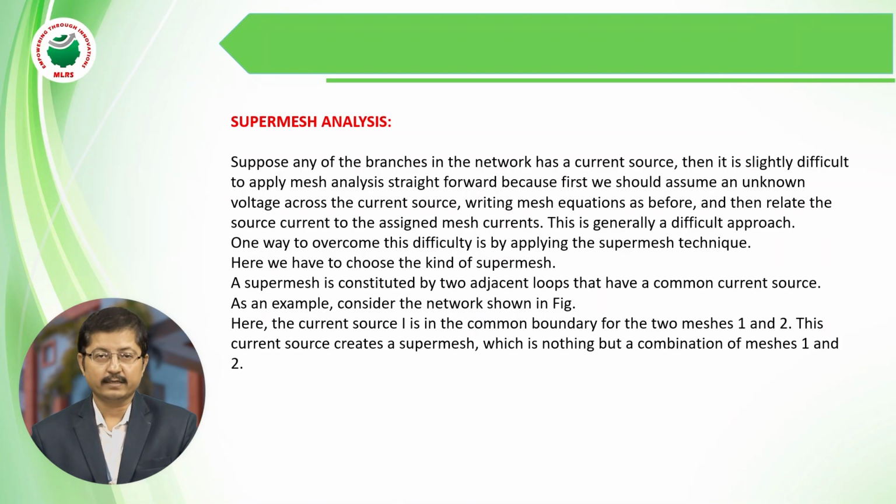Now coming to the next topic, that is super mesh analysis. What is meant by super mesh? Super mesh means that in between two loops, if there is any current source present, then it is very difficult to solve the problem. It is a tedious process. Again, we have to convert that current source into a voltage source, and it is time consuming. To overcome that, we have to go for the super mesh concept.